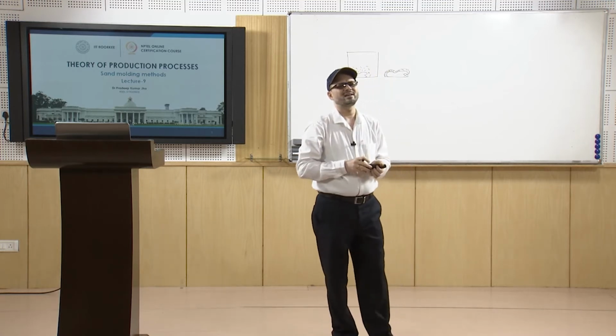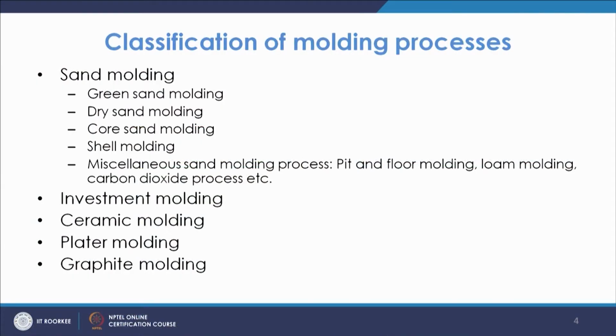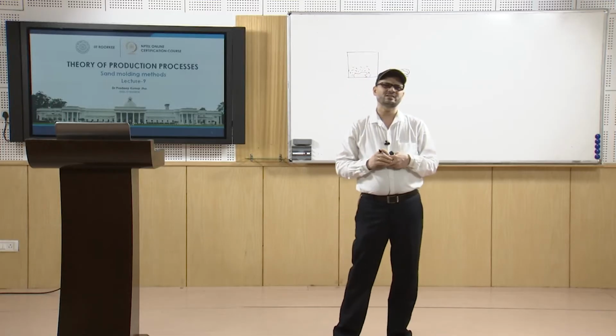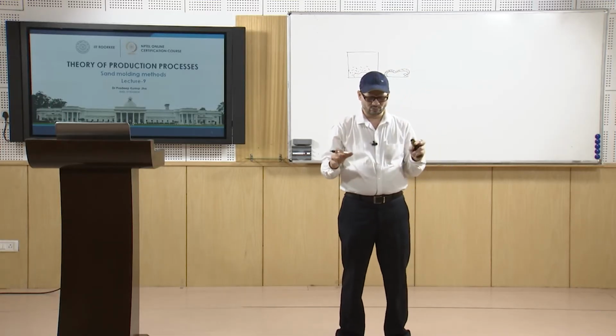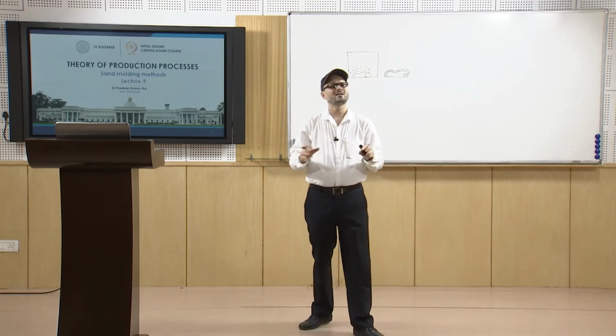You have miscellaneous sand molding processes like pit and floor molding. This is used when you have very large size castings. Normally you cast them in the pits or in the floor, so that is known as pit and floor molding.